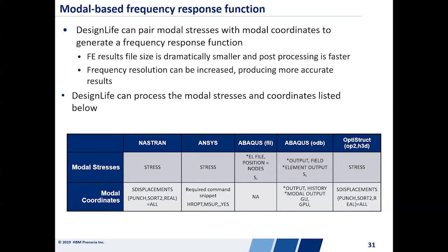What we can do instead is a modal-based FRF. Essentially, what we can allow DesignLife to do is pair modal stresses, so we can do a modal analysis in FE, with modal coordinates that could also be done separately in FE, and then with that information generate a frequency response function inside of DesignLife.